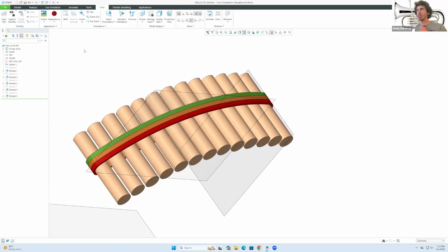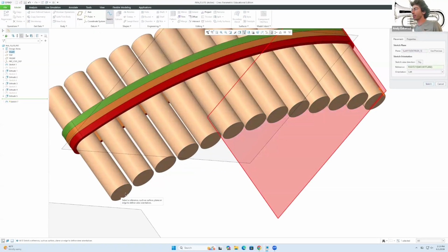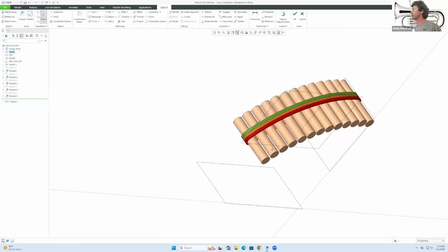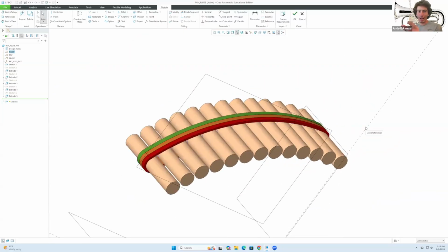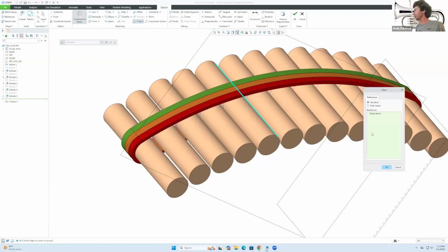Now that we have this defined, let's go here to model, sketch, face, click on sketch and whatnot. And now we need to trace a lot of those circles, and we need to just expand them slightly. So how do we do that? Well, I'm gonna go here to construction mode. Then here go to my friend there, where are you, project? And I just realized that I could go for this one that's called all curves on feature.